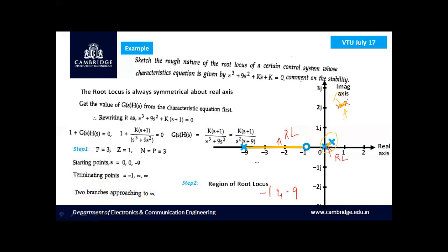We have a region here in which we have two adjacently placed poles and it is in the region of root locus. Therefore, a minimum of one breakaway point exists here, and that location we can also identify, it will be exactly at s is equal to 0. Even the location of the breakaway point we can identify in this example as we have a multiple pole at the origin. So one breakaway point exists in this example and the breakaway point location is at s is equal to 0. Moving on to the next step.